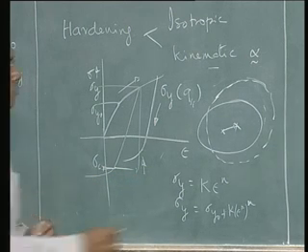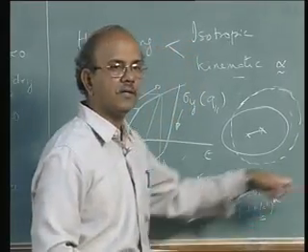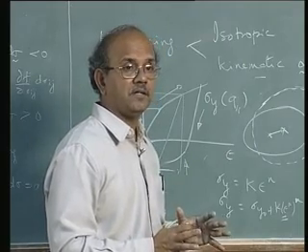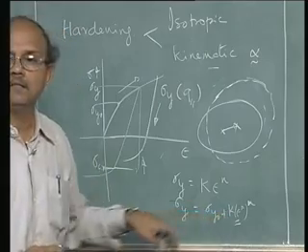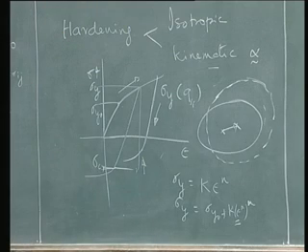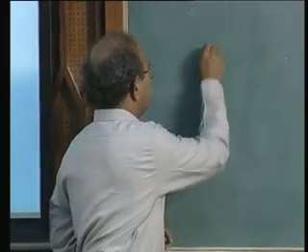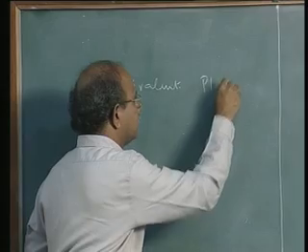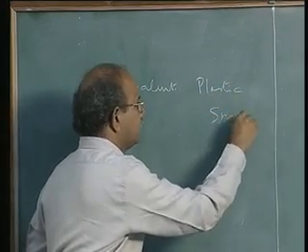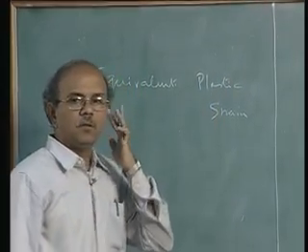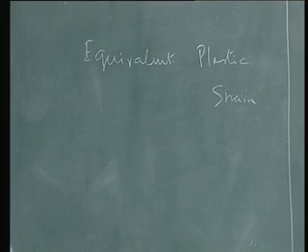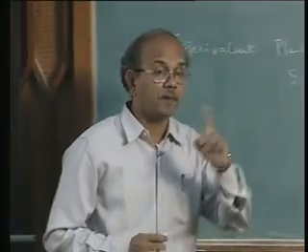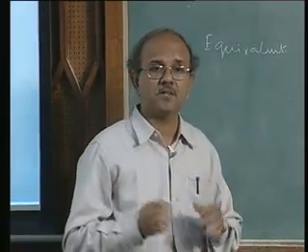Now, the question is, what is this εp when in a multi-axial case? So, we now define what is called an equivalent plastic strain, in order that we can understand the uniaxial case. So, what is an equivalent plastic strain? Now, what should be the condition for an equivalent plastic strain? Can you come out with the condition for an equivalent plastic strain from what we have as an equivalent stress?